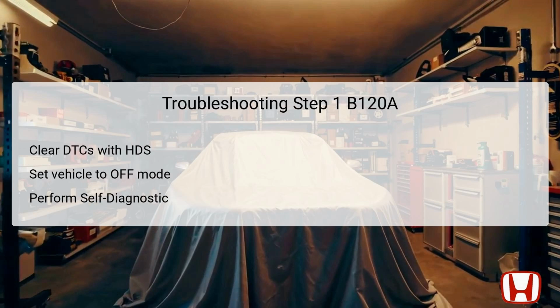The first step in troubleshooting DTC B120A involves using the HDS Honda Diagnostics system to clear any existing diagnostic trouble codes. It's essential to turn the vehicle to off, lock mode initially to prepare the system. After clearing the codes, turning the vehicle on allows the system to reinitialize. The next step is to perform a self-diagnostic function with the HDS or directly with the climate control unit to assess if the DTC reappears.